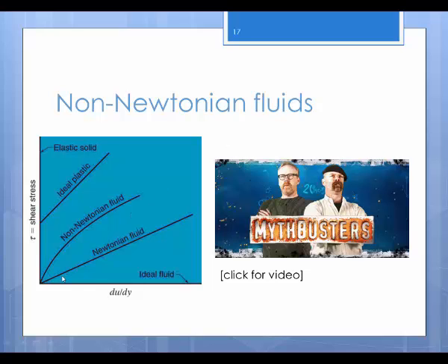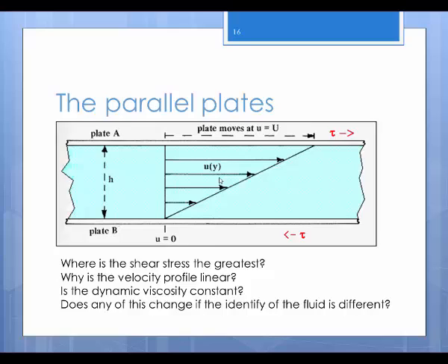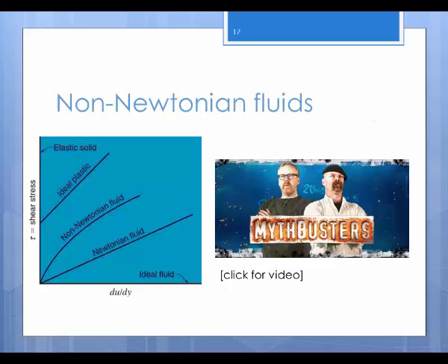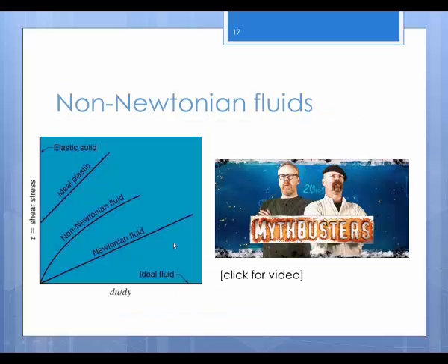And when you look at Newton's law of viscosity here, embedded in this, Newton's law of viscosity is true for every fluid. The challenge is, is this dynamic viscosity always the same? We know it can change some with temperature, but what else could it change with? The concept of a Newtonian fluid, I think when Newton formulated this idea, he had this idea that maybe some atmospheric temperature, climate conditions will change this, but other than that, it's going to stay the same. And for a lot of fluids, it does stay the same.